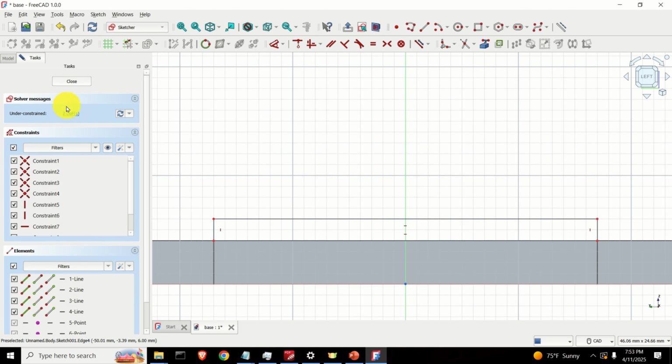Note over here that I'm not going to constrain this rectangle over here. I'm doing this for one particular reason. Namely, if I would now constrain everything inside of this two-dimensional sketch, this video tutorial will not last 1 hour, it's going to last 4 hours. Consequently, I'm just going to constrain only the necessary and essential parts, and these parts will be mainly the sliders or something similar to that, something where I need to precisely control the dimensions. Over here, the dimensions are not going to change while you're extruding.